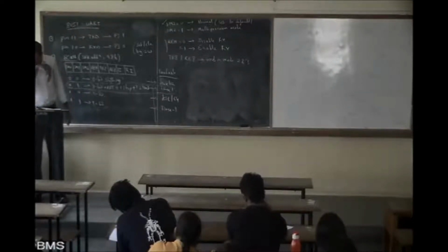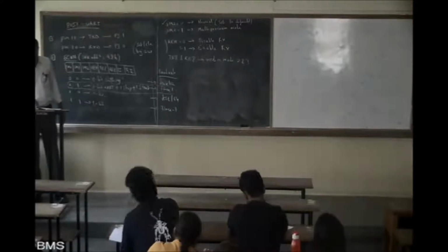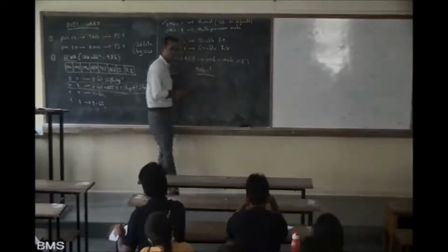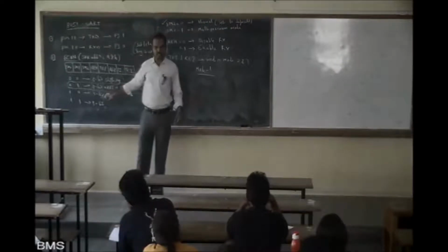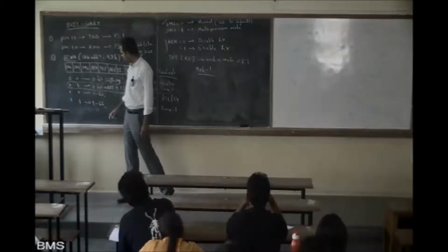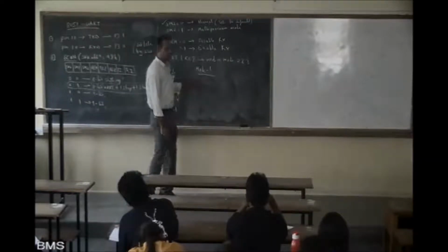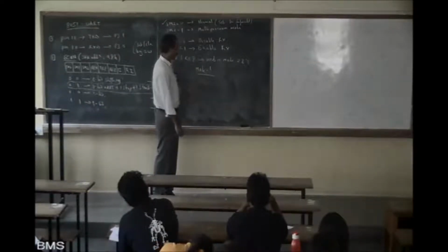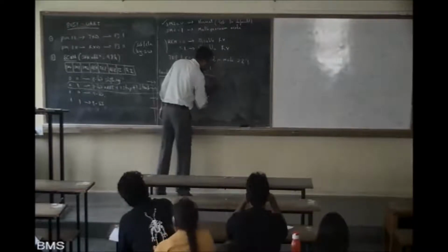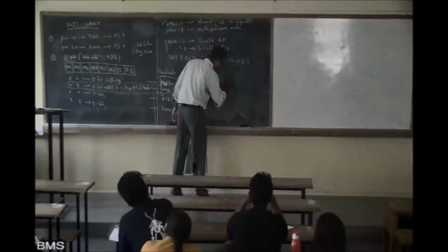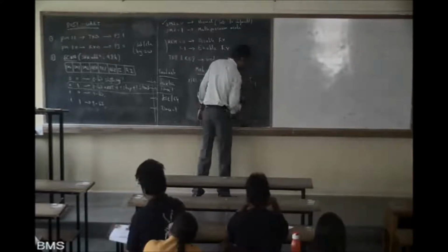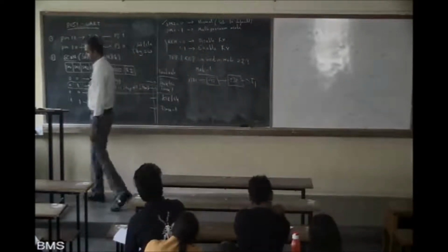Now the very important part. In mode 1, only this is there in your syllabus. Mode 1 should not be confused with timer mode 1. This is serial communication mode 1, SM0 and SM1. When it is in mode 1, your XTAL is divided by 12, then divided by 32 and given to timer 1. Please write this.